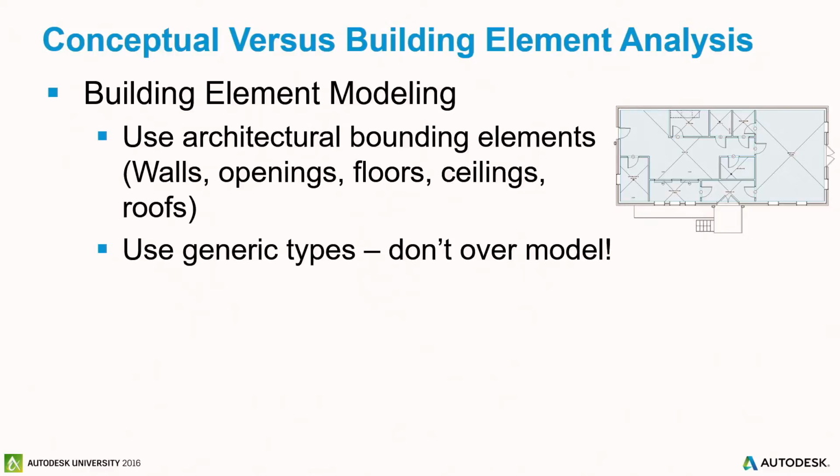They want to show the client, in the preliminary stages of design, what looks like a finished model with all these pretty materials and everything else. And if you haven't worked out the concepts of the building to make sure it's working the way you need it to, you really can over-model sometimes too early. So it really depends on what type of model you're doing. Do I need the materials for the thermal properties? I could get away with just a generic wall in some cases.